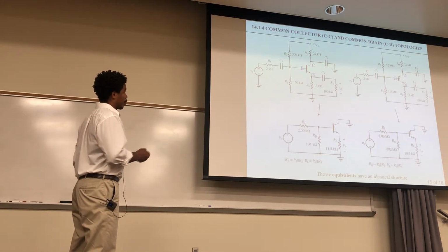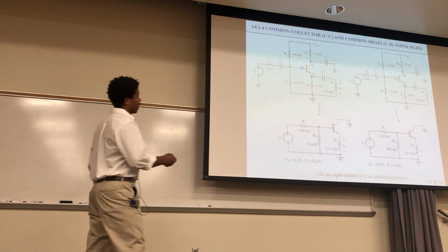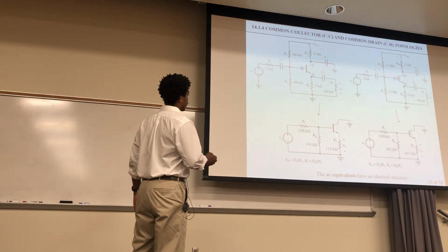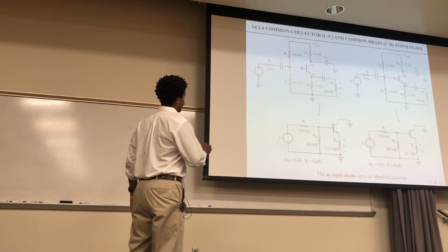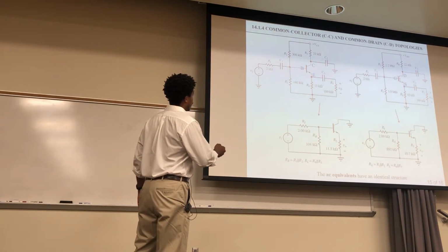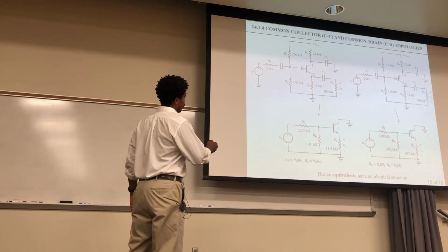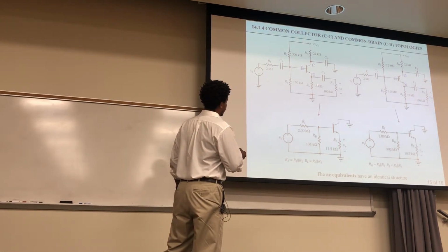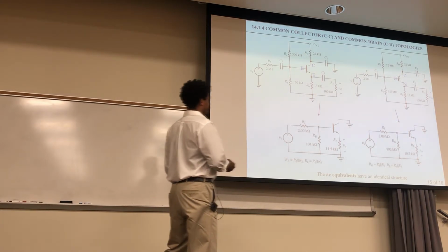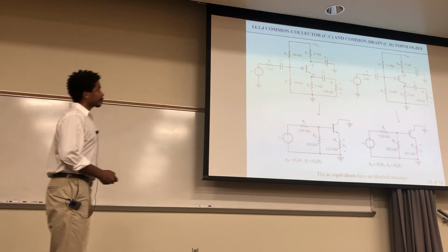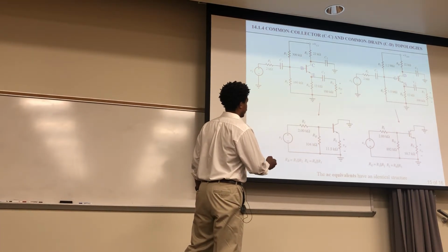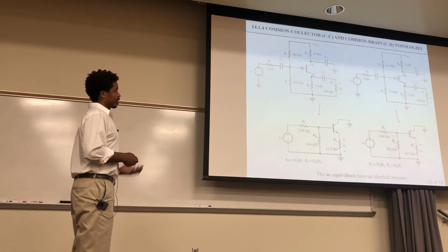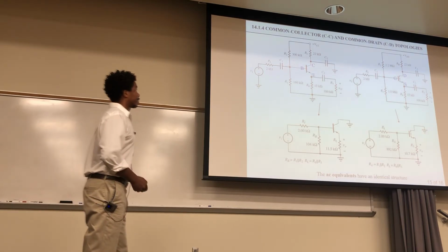So here's the simplification going from this CC right here and CD from here to here. Again, these right here are short-circuited. That's why this one just goes straight to ground because of that right there. And this right here is shorted. So this voltage right here is the same voltage that's going to be across this R6. Okay, but the load's going to change, right? This is 100K, this is 13K, and now you have this load which is 11.5K. So those are parallel after that. And a similar thing goes on over here. Okay, but again, the AC equivalent circuits have identical structures in both cases.